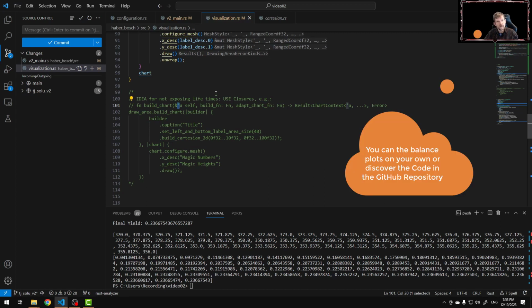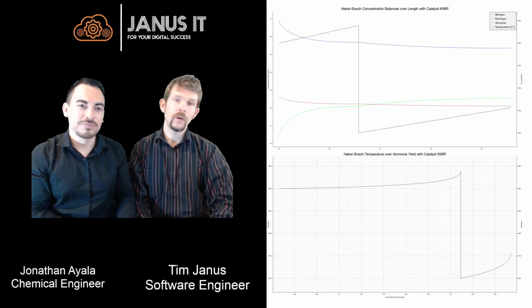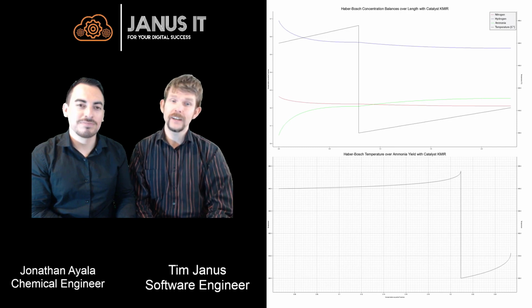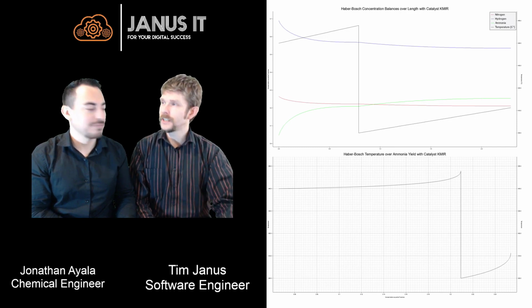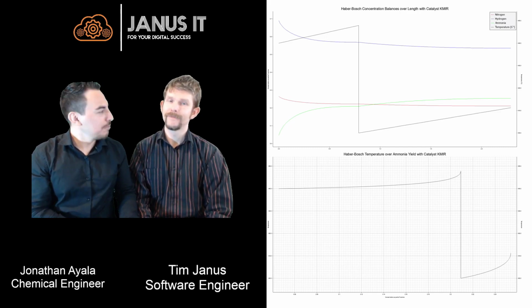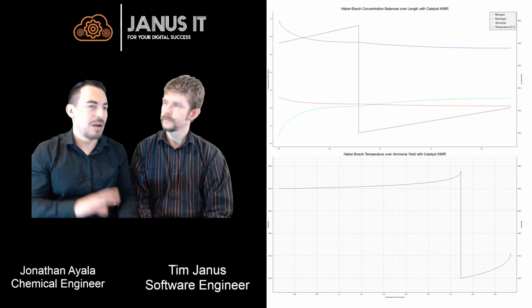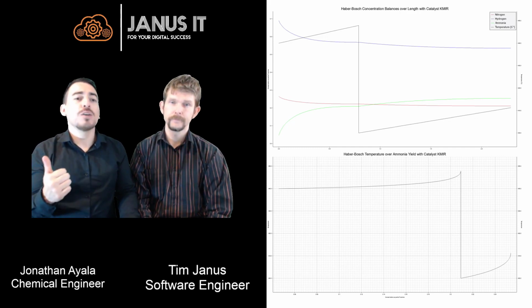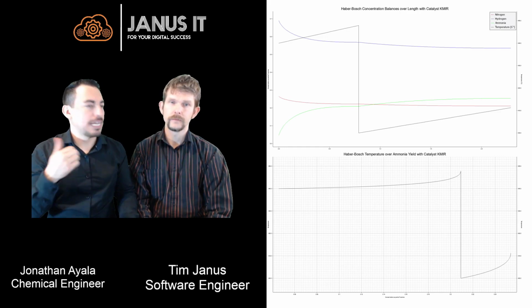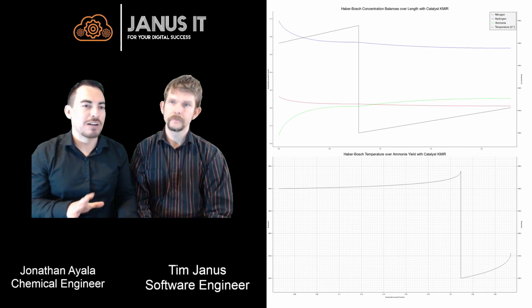The concentration balance plots are open, but you can look at the solution, and we will now join Jonathan. Hey Jonathan, great to meet again. Now, after we are capable to render these kinds of diagrams, what would you say are the next steps? Hi team, these diagrams look promising. Thank you. For an in-depth analysis, we would now investigate the sweet spot for our degrees of freedom. So first we have design parameters like the type of catalyst and the length of the reactor. Once we fix them, we cannot change them without significant cost.